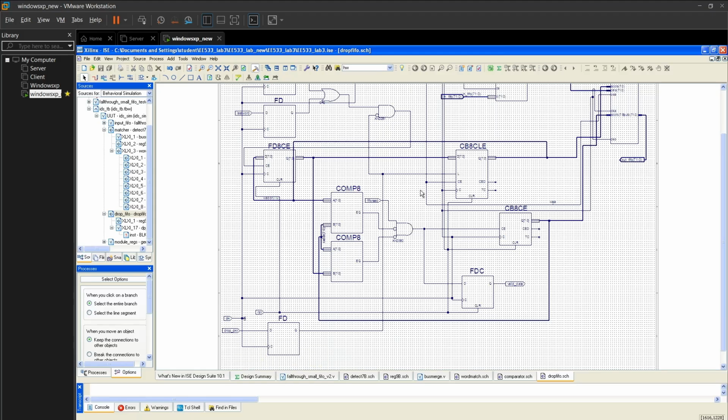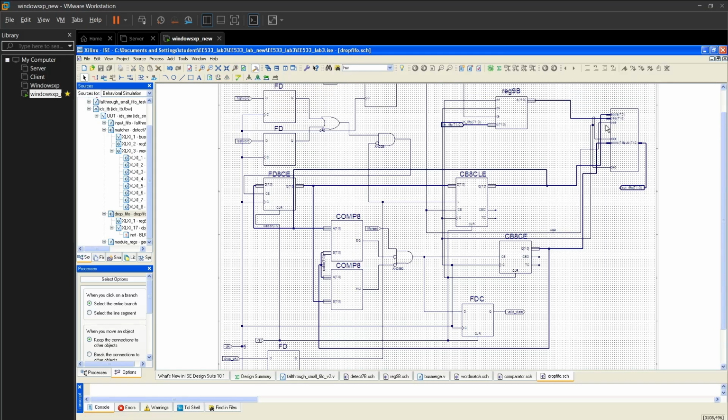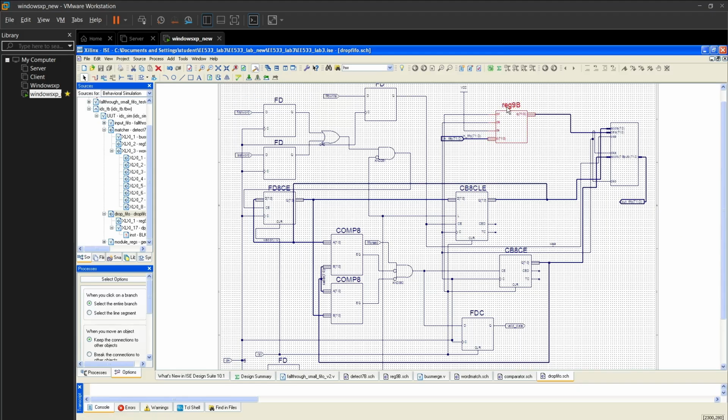If it's a drop packet, then we'll enable our counter for writing in the memory. This is our memory. We are using port A for writing in the memory and port B for reading from the memory. We also have a 9 byte register file for sending the data into the memory. So that's the main design here.